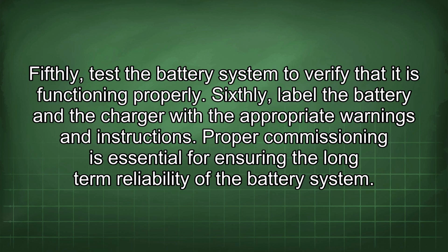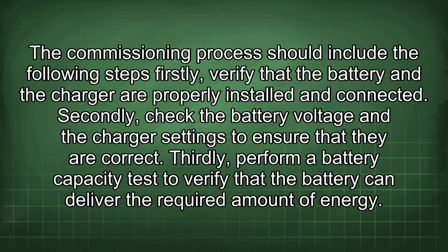Proper commissioning is essential for ensuring the long-term reliability of the battery system. The commissioning process should include the following steps. Firstly, verify that the battery and the charger are properly installed and connected. Secondly, check the battery voltage and the charger settings to ensure that they are correct.